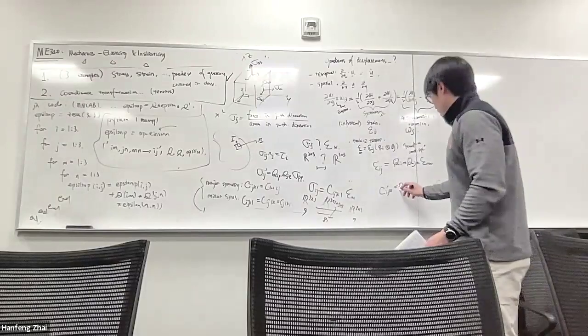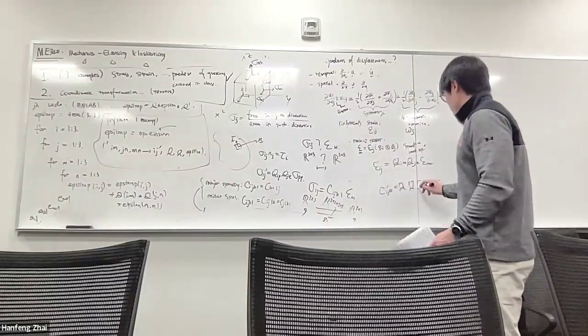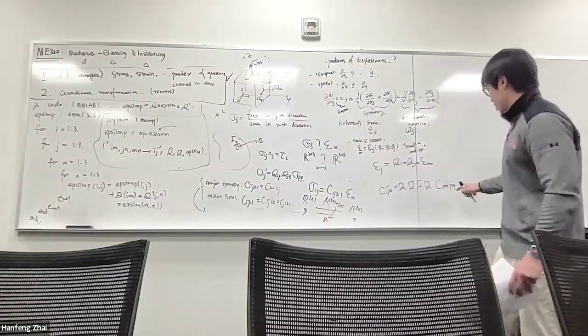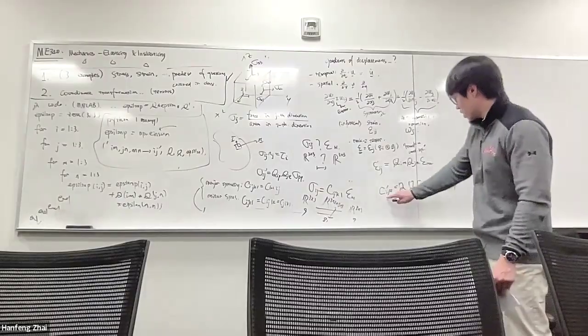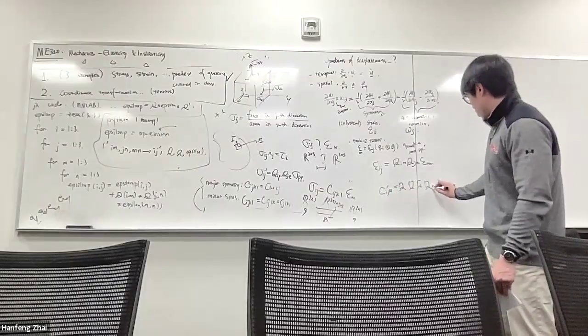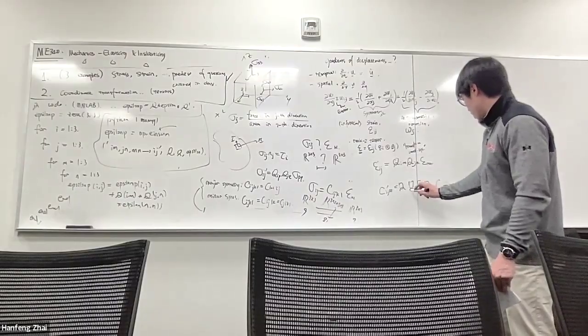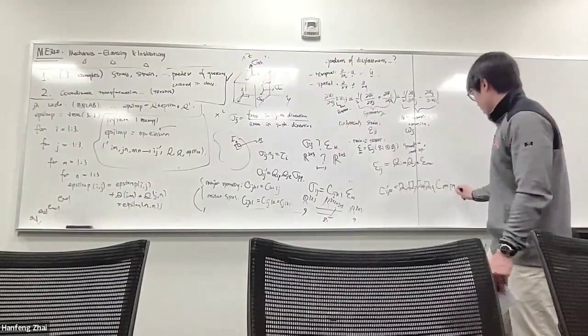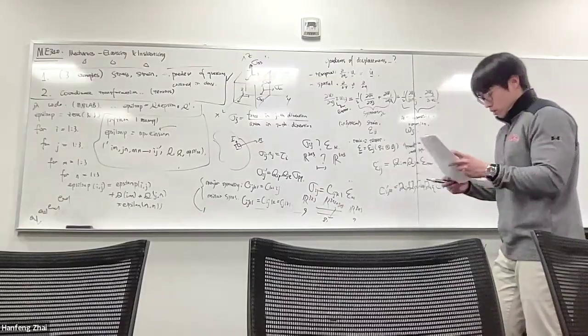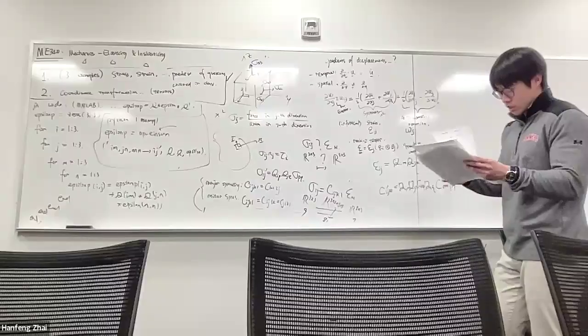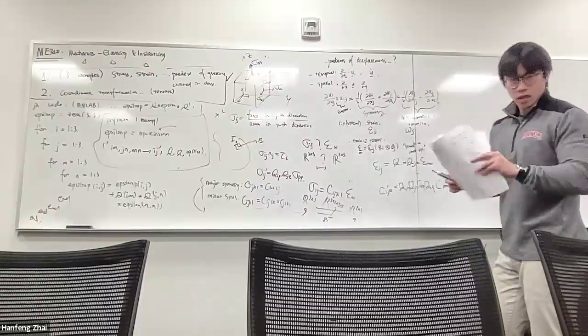Just apply the rotation matrices that take care of indices q, p, n, and m. So from q to l, from p to k, from n to j, from m to i. This is how you transform the coordinate system to represent the same fourth order tensor. And so for now,